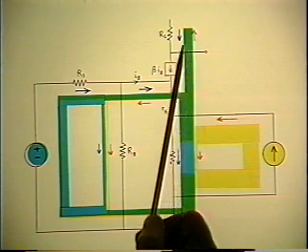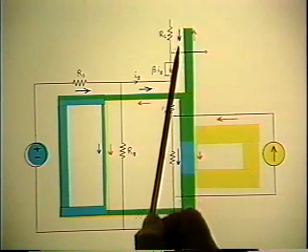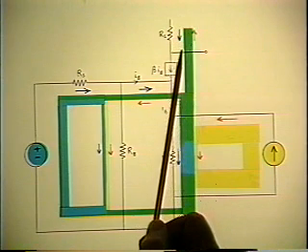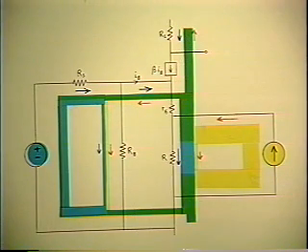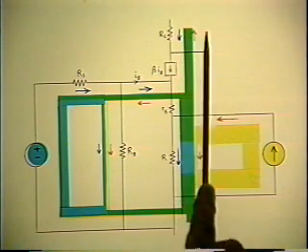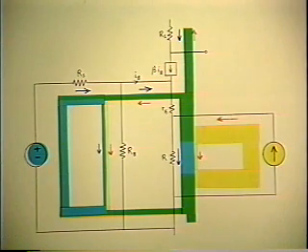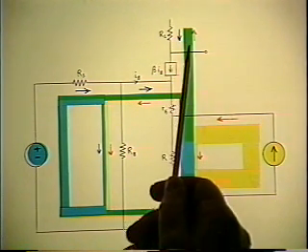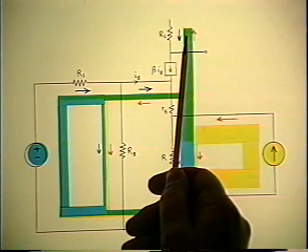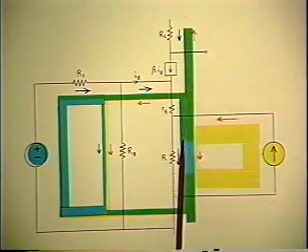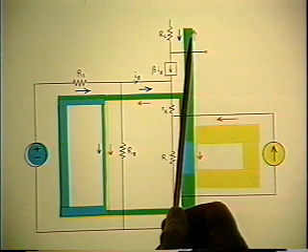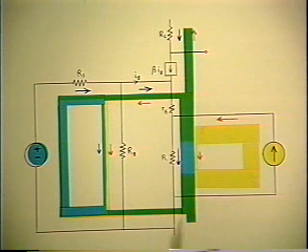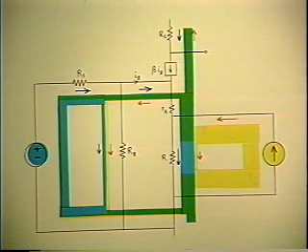And you see what has happened is that if you look at these two arrows, the blue arrow is down, the yellow arrow is up, and they're equal in magnitude. This is how you get the null. You've made those two currents equal and opposite by appropriate adjustment of those two sources. So they cancel out. That's how the null develops. And you see the propagation of the null now becomes obvious, because the only way you can get a null at the output of the transistor is to have a null at the input as well. Namely both the base and the emitter.